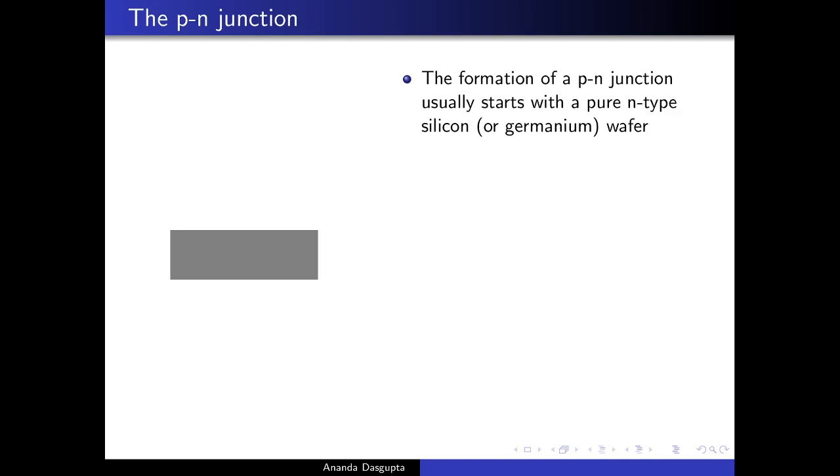of pentavalent impurities. So what would happen is that this silicon wafer or silicon crystal will have some amount of imperfections in it, some gaps where there should have been silicon atoms but there aren't, and the pentavalent impurity atoms would diffuse through the crystal and go and sit in those locations. How strongly are you doping?